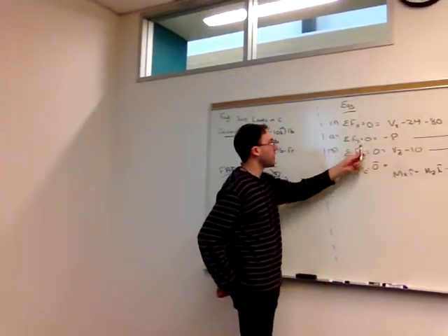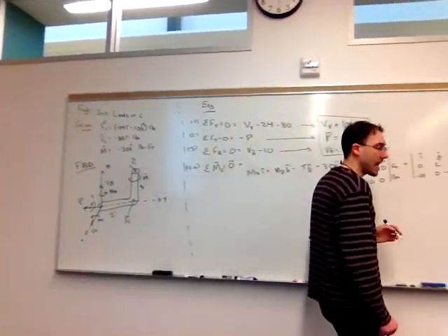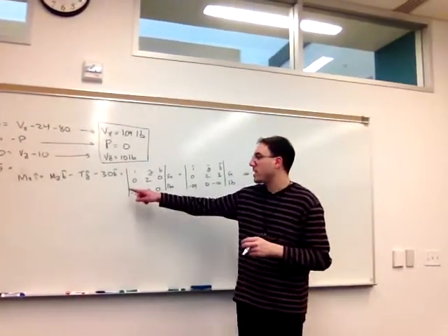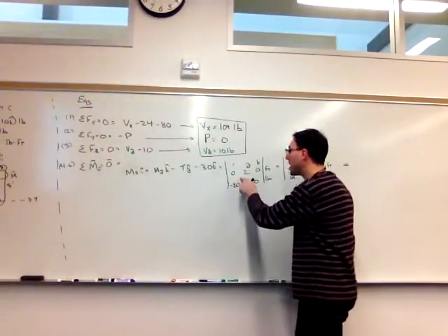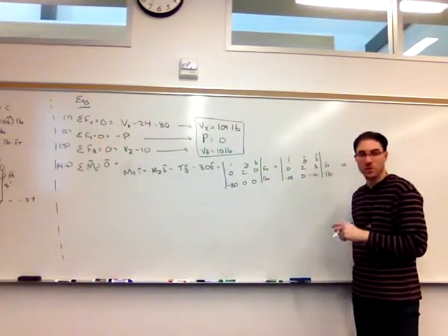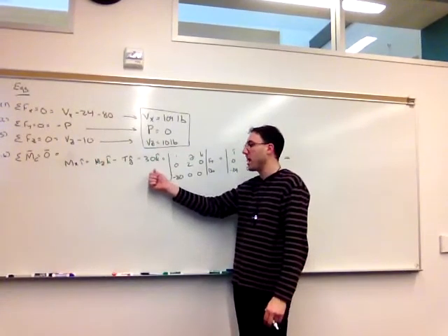That did not appear in the force equations. It does, however, have to appear in the moment equation. That negative 30 we put right in here. Everything needs an i, j, or k with it. It appears out here as a couple, not in here as a force. So 4 couples in this case, 3 of them internal, 1 of them applied.